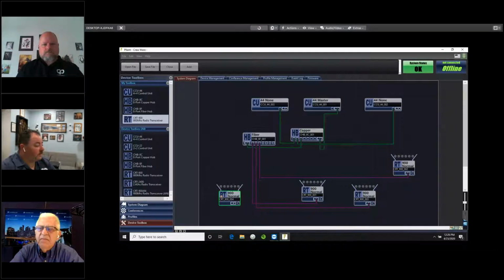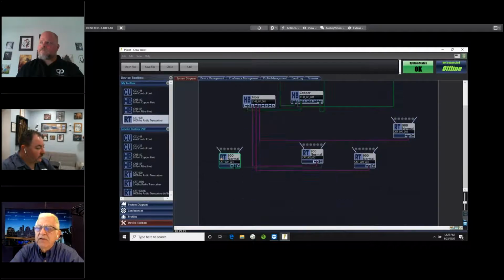Yeah, let me just describe that a little bit. But first, we had a question from Ryan. Can you daisy chain antennas off an RT or a hub? Yes, if you're going fiber to a location and you power that hub or power the antenna it goes to, then up to 7 antennas can be powered off of that antenna's loop through. Correct. And then after 7 antennas, you just power another antenna with a plug in the line, and you can power more.